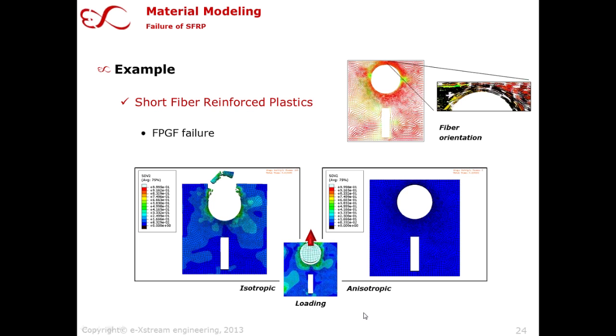Whereas if we turn to the failure behavior with an anisotropic model, we see completely different behavior, and this is taking into account the local fiber orientation. And if you just imagine what this means for an impact scenario, if we just want to discuss energy absorption and everything like that, you see the implication. It's definitely important to get the description right.